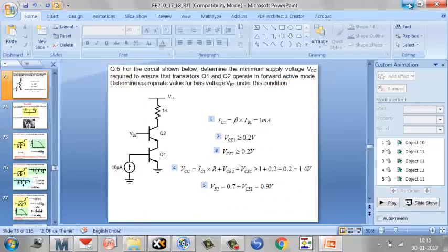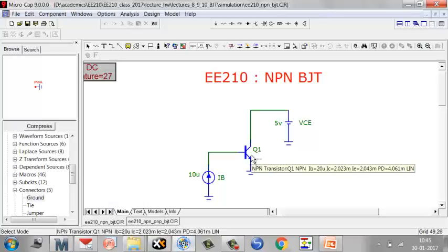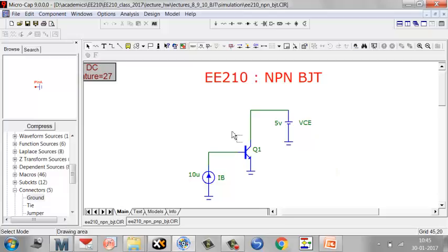No, there is no quiz, don't worry. So what we do is, we go and do a circuit simulation. See, these are simplified results, right? I've used a simplified model, 0.7 volt, and I said when you go up to 0.2, the device is not in saturation. So the next thing is, not in an exam, but in real life, the next thing is to go ahead and simulate your circuit and see whether the circuit is working fine or not.